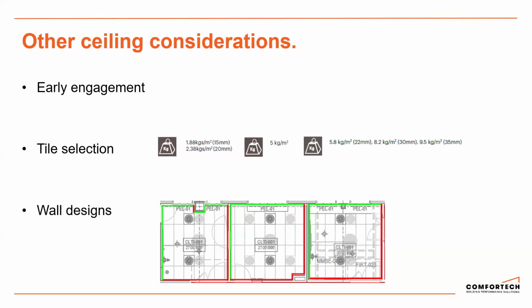The nuts and bolts of what came out of it was we were able to reduce the need for another structural member to hold the ceiling up. That was incorporated into the original structural beam that was being installed or designed for the mechanical services. So it reduced a lot of time in terms of labour. It reduced a lot of space that was required in the plenum space, so it created openings. And overall, a really good example of why it's such a good idea to do things like that.